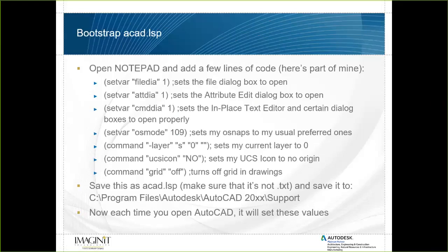Let's see, been a while. We'll have to dust off those skills. Have a good resource for it? Not really. Lisp hasn't had any updates since the 90s. So most of the books you find are dated late 90s. The best place to probably go is if you've got, in AutoCAD, you still have the Lisp function. You can type in VLIDE to bring up your Lisp editor, and you can go through there.